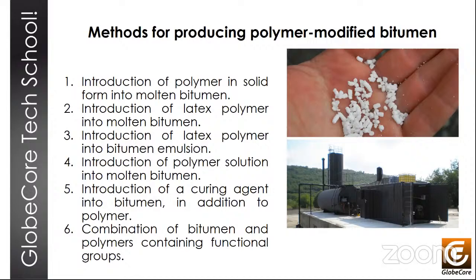And in the production of modified bitumen, two processes are generally distinguished and used. There's the continuous production process and the batch production process. In continuous production, hot bitumen and polymer, be it in powder or crumb form, are fed into a low fineness premixer with precise control of the flow. At this stage, the bitumen is wetted with polymers. And after this pre-mixing stage, the bitumen polymer mixture passes through a mill with a high degree of fine grinding to achieve the desired mixing quality.